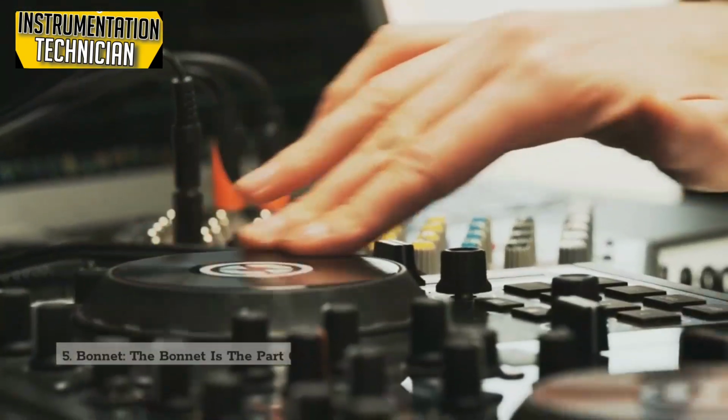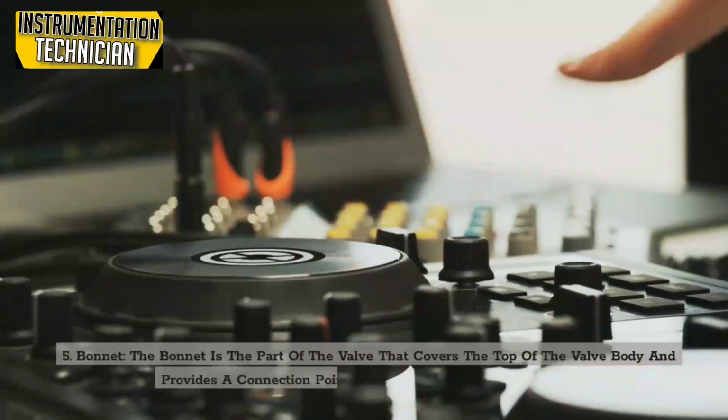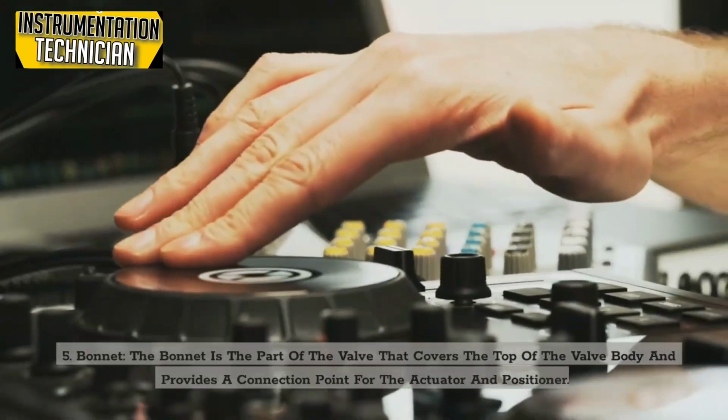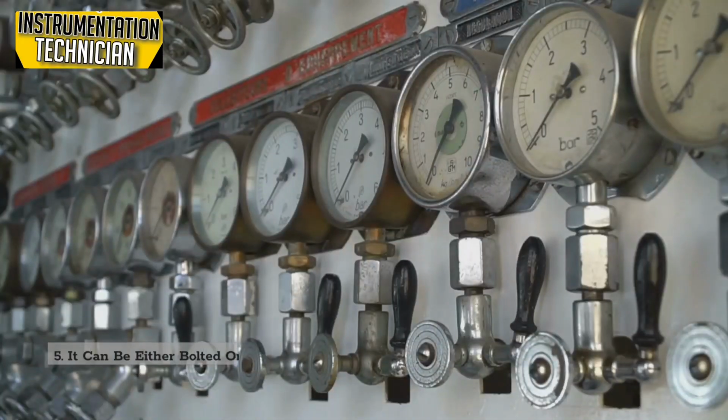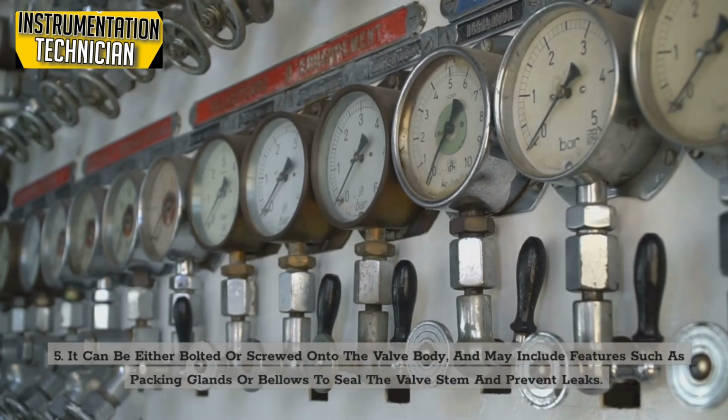5. Bonnet. The bonnet is the part of the valve that covers the top of the valve body and provides a connection point for the actuator and positioner. It can be either bolted or screwed onto the valve body, and may include features such as packing glands or bellows to seal the valve stem and prevent leaks.